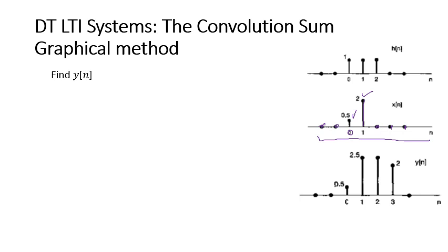As far as the impulse response is concerned, it has three non-zero samples, as can be seen here in the figure on the top right: at 0 it has amplitude of 1, at 1 it has amplitude of 1, at 2 it has amplitude of 1, and for all other values beyond 2, or beyond -1, these values are 0. So it consists of only 3 non-zero samples, and all of them have equal amplitude.